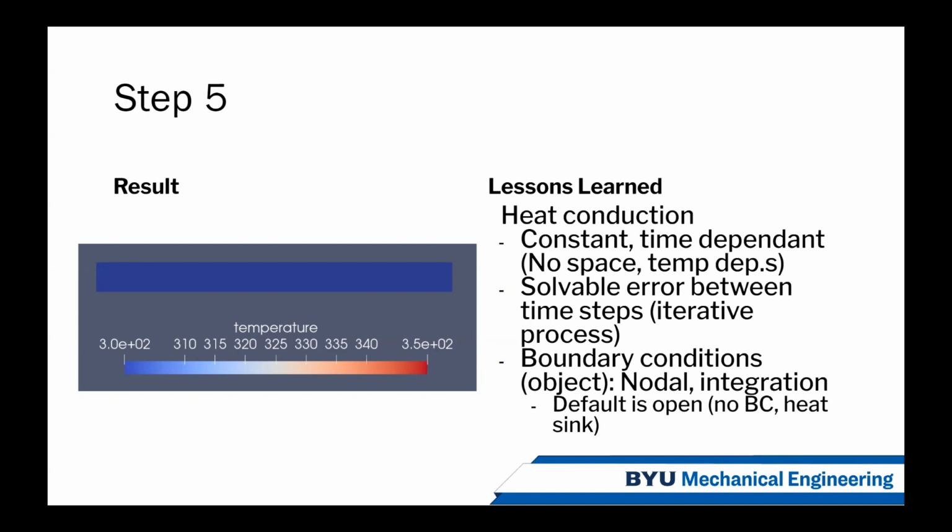We cannot make it space dependent, but if it is dependent on something, then we can have an iterative process where it calculates over, say, time, which is the most likely scenario, what the new conduction coefficient is, or whatever their application is. There is going to be an error because it is iterative if we're not integrating.